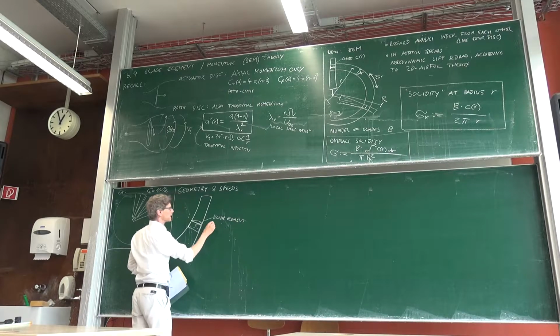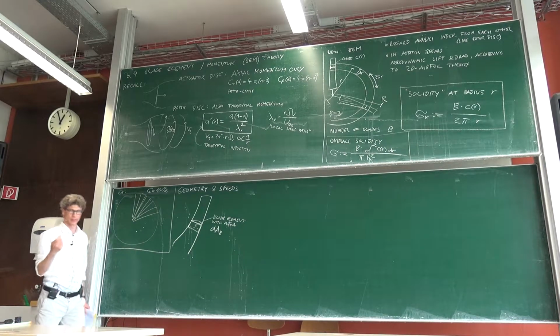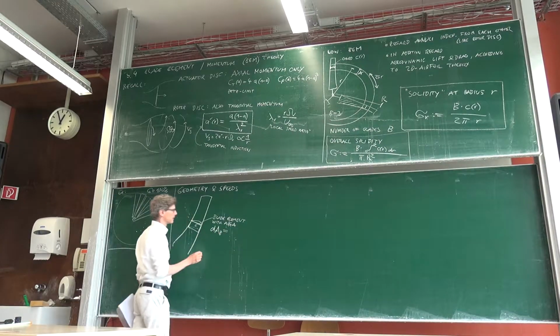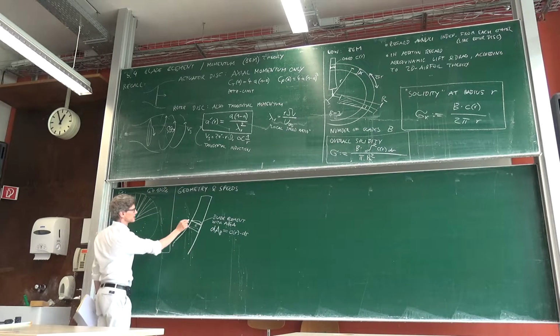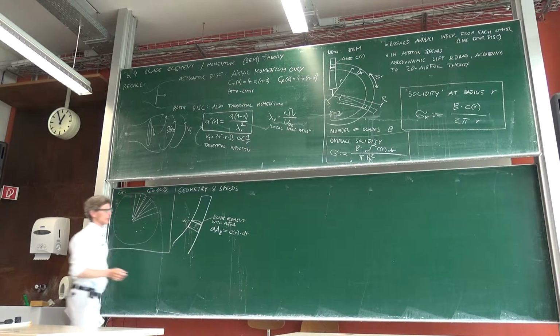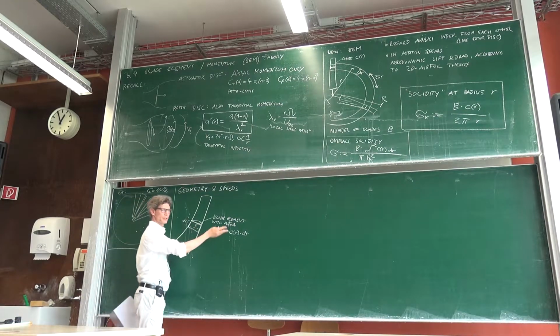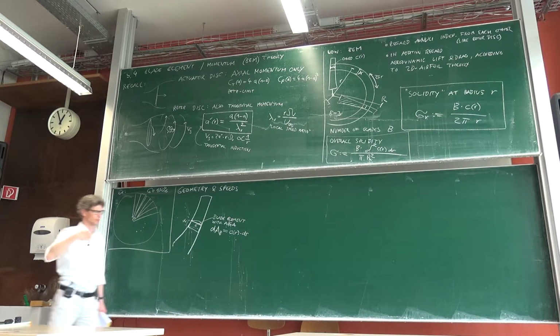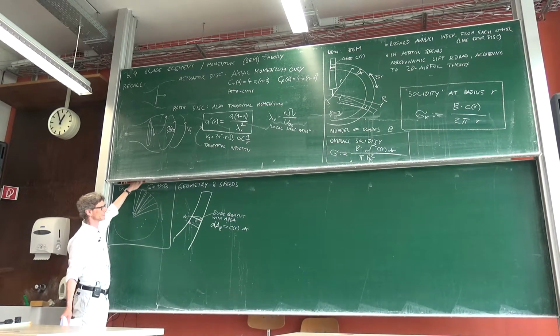And of course the area, what would be its area? I call it dA_B for area of the blade, right? We had that language before. The area of the blade is of course nothing else than the chord length times dr. dr is this little distance here, right? And whenever something is infinitesimally small in this direction, I use just the usual d, and if we integrate over it, we get a real number, a number that's finite and not infinitely small anymore.